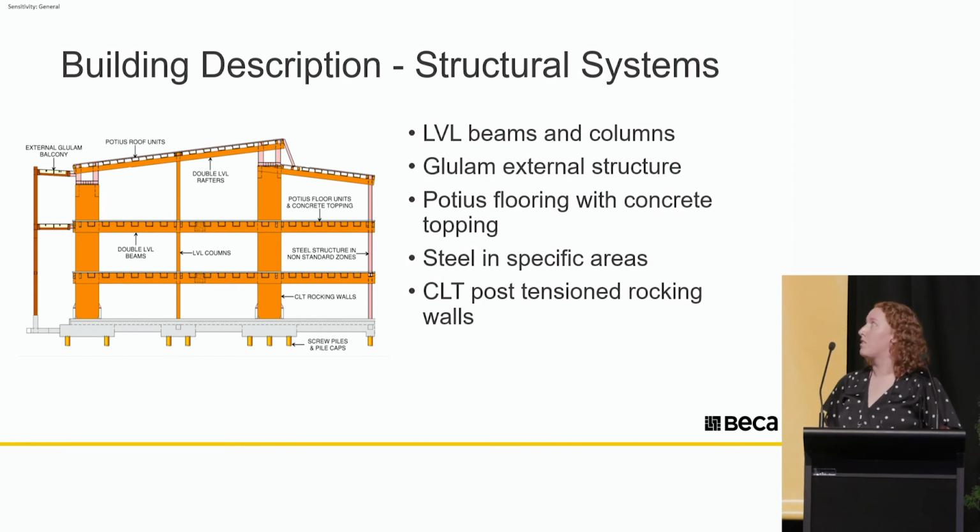This is a typical cross-section of Building 1. The timber is the primary material with Alveolar beams and columns, a Posi-Strut panel floor system, CLT walls, and glulam for all the external structure. Steel and concrete were brought in when the structure moved outside the uniform layout that was required to make timber work. And this included a concrete floor topping due to the broken diaphragms around atriums, steel columns around the double height spaces, and steel for stairs and canopies.